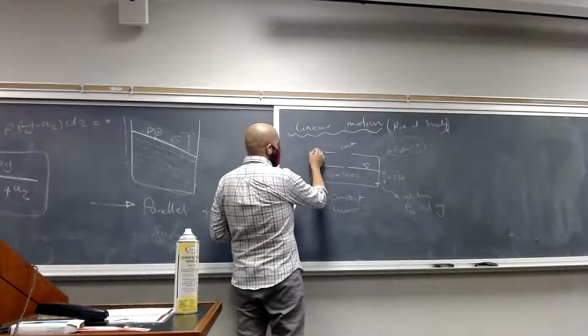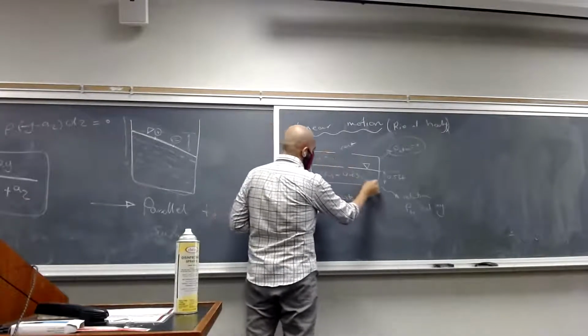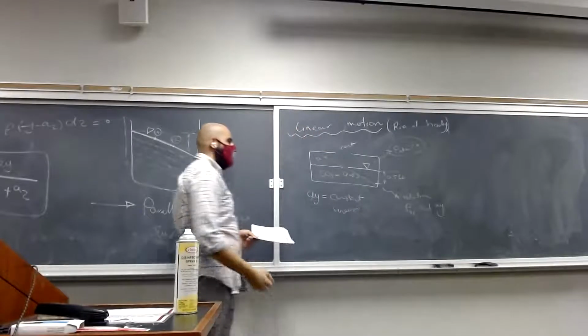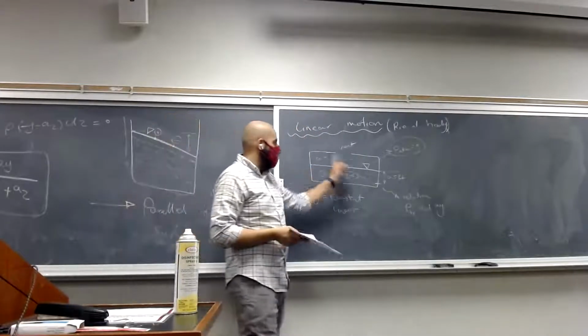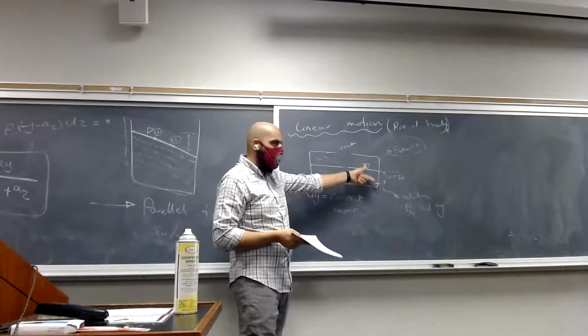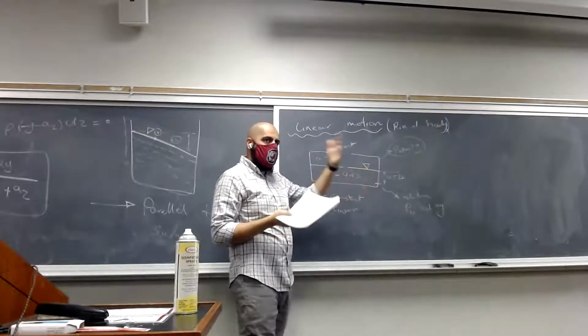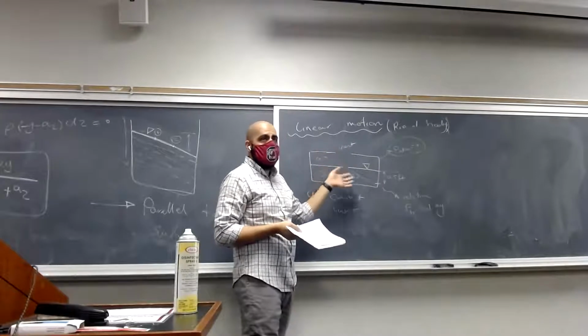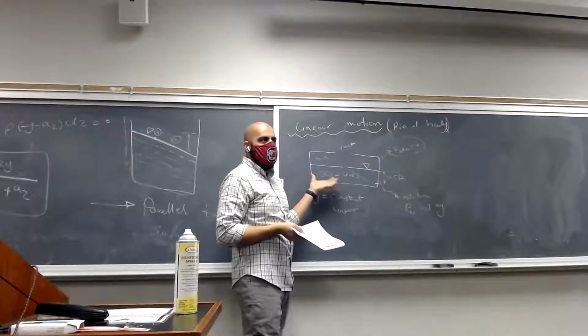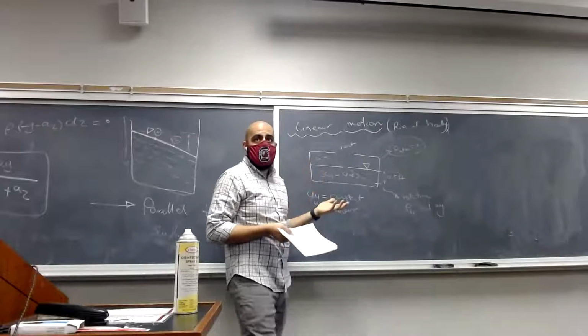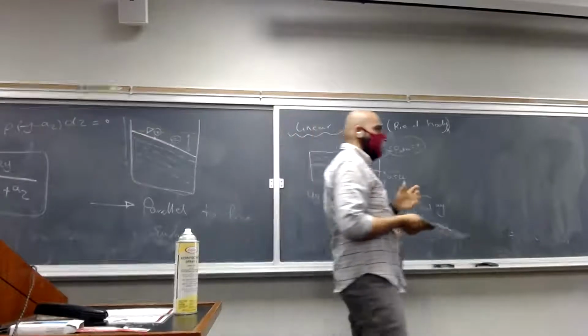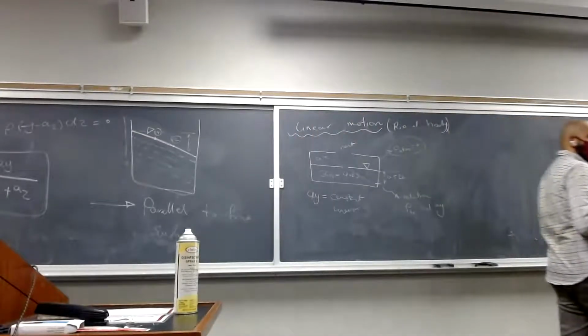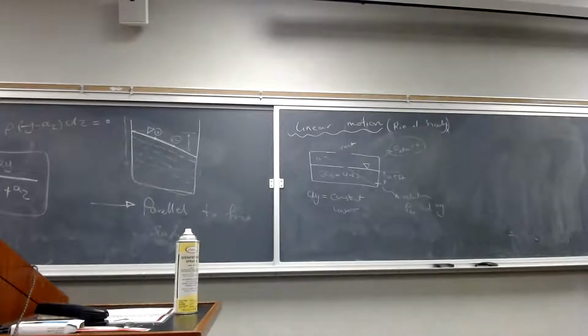We want to find the maximum acceleration at which this free surface will drop below the pressure transducer. What does it mean? It essentially means that we won't be able to measure the pressure inside the tank anymore for that fuel, because the transducer doesn't have any contact with the fuel inside. Okay, so what is the equation we have?